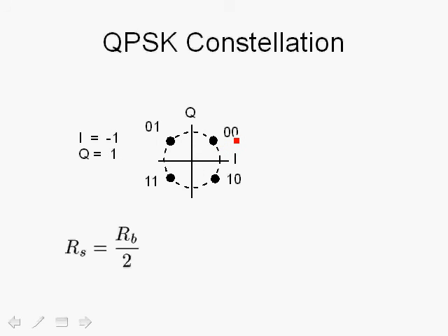If we have 2 bits, we have 2 to the power of 2, or 4 possibilities, which are shown over here. And we associate the bits with each coordinate, with each symbol. For example, 0, 0 and 1, 0 for this coordinate, and 1, 1 for this coordinate over here. So we have 4 possibilities that represent 2 bits of information. So 2 bits of information can be mapped to a symbol in the constellation.